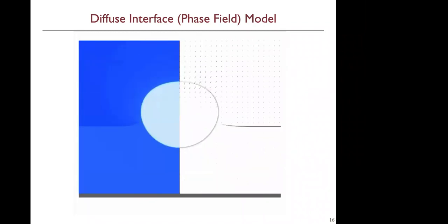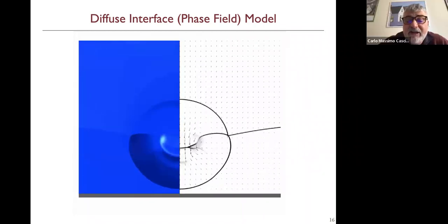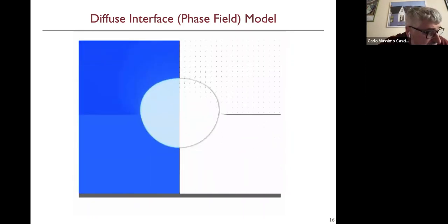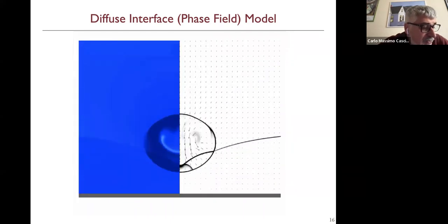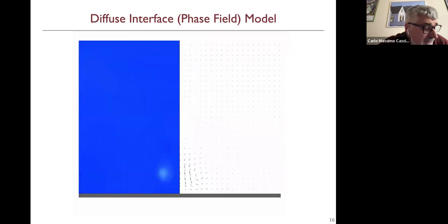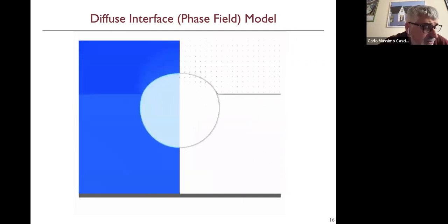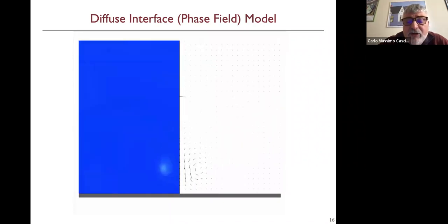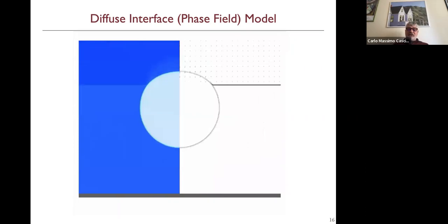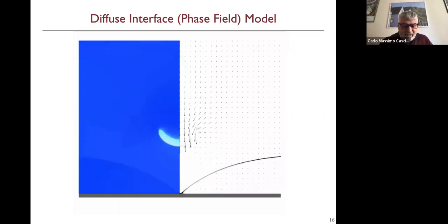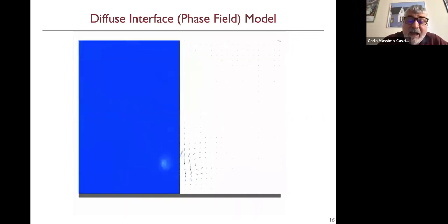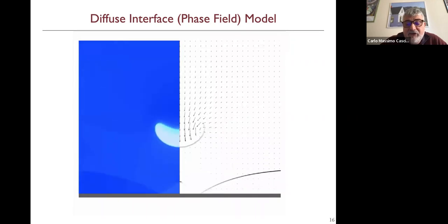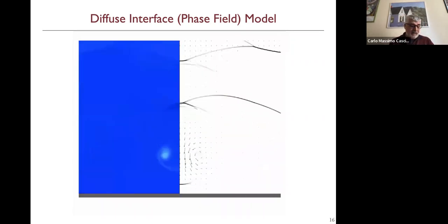It is important to notice that those apparently innocent arrows that represent the velocity of the fluid are in fact very, very fast. We are in the presence of a strong compression wave. They are almost shock waves. It means that the velocity of the fluid over there is of the order of the sound speed in the liquid, which, as you know, is rather high. So what you have is that during the collapse, you develop very intense temperatures and pressures and a very strong impinging jet, which combined together are responsible for the damage of the material over which the bubble collapse takes place.